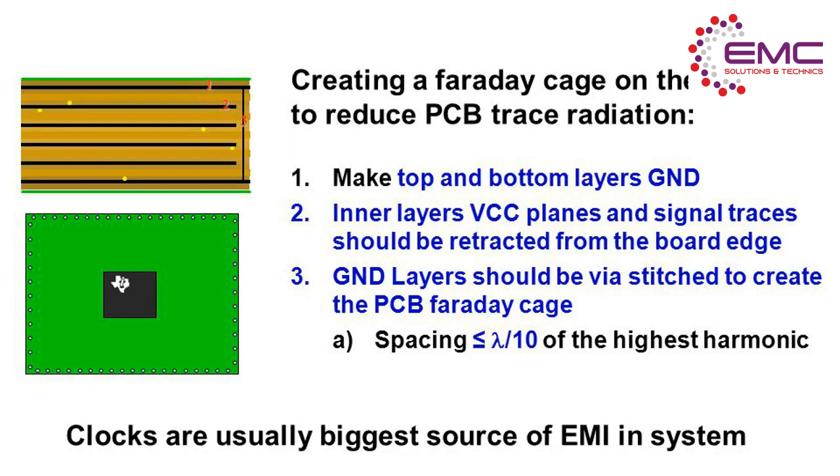Using a Faraday cage is another good mechanism for reducing the problems caused by EMC. A Faraday cage is formed by stitching the ground on the complete periphery of the PCB and not routing any signal outside this boundary, see figure. This mechanism restricts the emission and interference from or to the PCB within or outside the boundary defined by the cage.